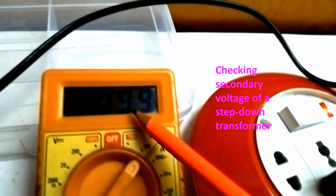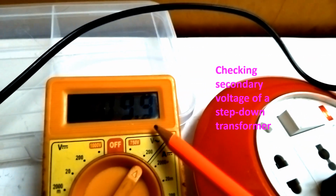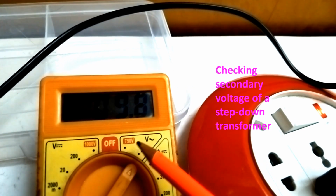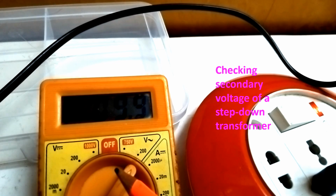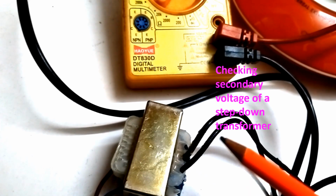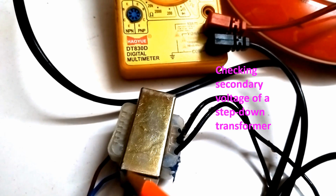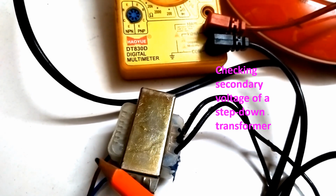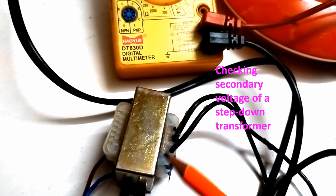You can see that the step-down voltage, the voltage in the secondary, is only 9.9 volts. So this is the step-down action of a transformer. This transformer has stepped down from 230 to 9.9, approximately 10 volts. So the turns ratio in this transformer will correspond to that. The ratio of the turns will be like 230:10.